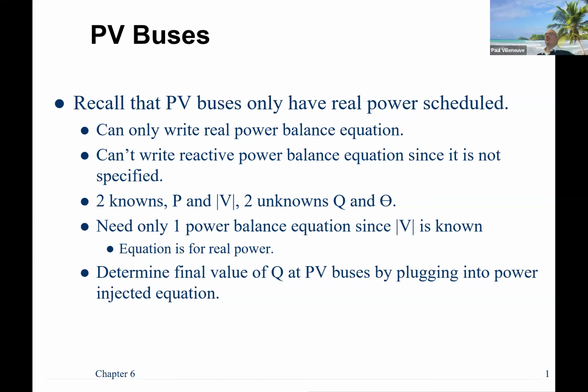So in a PV bus, it's trying to represent what you would typically see if you were a generator. Most generators, right, they want to run as much output power as they can to maintain their system at maximum operation. They sell the most amount of kilowatt hours, they're going to make money. So they want to schedule or set what their output power will be, because again, that's what they get compensated on. And because they can directly control the voltage, they'll adjust their voltage regulator or their excitation systems to, within reason, maintain the voltage at their bus.